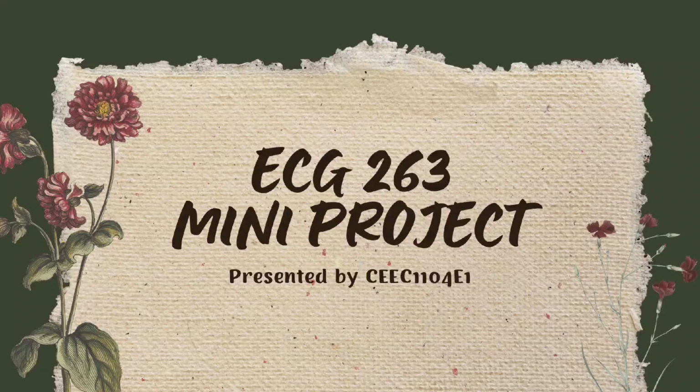12.26% for A, 12.5% for B, and 12.64% for C. This is an important metric since it impacts the strength and compaction of the soil. When the soil is compacted, it can reach its maximum density and stability when the moisture level is within the ideal range. Since standard equipment was not available, we had to create a core cutter procedure for the field density